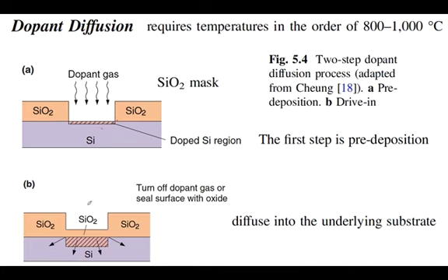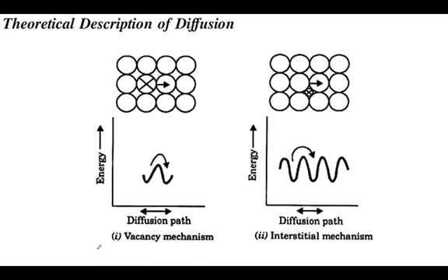Now when you heat, you basically cap this part. So you basically grow and then you cap by silicon dioxide again. So you grow silicon dioxide and then you heat them. Therefore this part of the silicon will be doped depending on the kind of atoms that you had grown. So this is one of the ways that you can dope the silicon material.